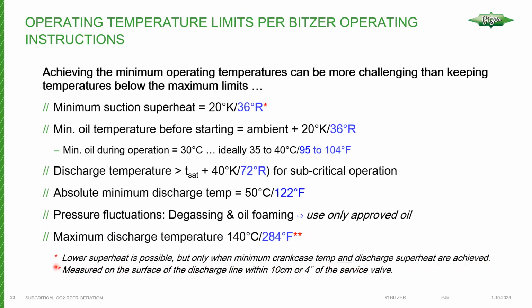And any of you who have participated in past training seminars know that I talk about discharge superheat a lot, even with HFC systems. It's quite common out there that we see systems operating with low discharge superheat. And you can have a few degrees of superheat entering the compressor, but it may not be enough. The discharge superheat's got to be high enough. And with CO2, generally speaking, the numbers are higher.